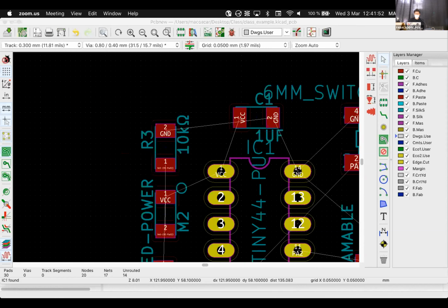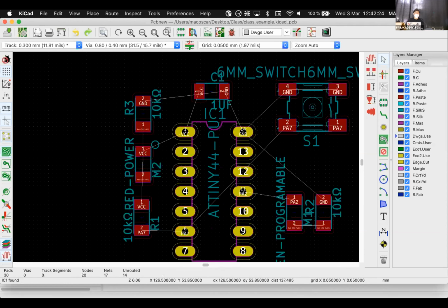By default, let's say we would try to just keep all the components on the same side and not get into this mess because it's a little bit more confusing. But just so you know, okay? As I would do it now, I would put the component on top and solder from the top, even if it's not the best. How you would do it professionally is that you put it like this, and then you have all the SMD components on one side, and the microcontroller comes from the bottom and goes through the different paths.